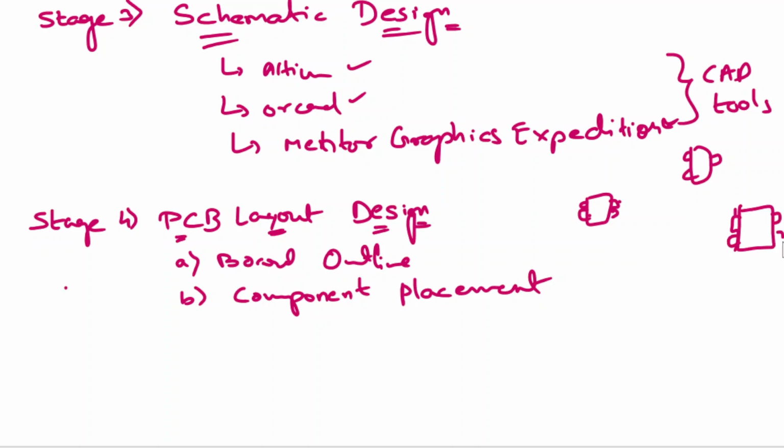Now earlier you have routed these components properly, but because this component is already routed first, now you have to route this also here. Because of this, the length between these two is minimum, agreed, but it is not sufficient, it has to be closer. But you are not aware of what the minimum or maximum distance between these two ICs should be. That you need to calculate. That is known as the critical length of the transmission line or PCB trace.